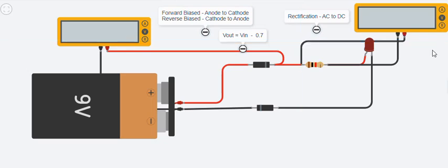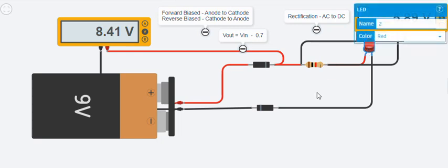It's usually called a current limiting resistor. Now 5.89, right? Yes. So 5.89 is what this is responsible for. The leftover is being shared by the LED and this diode. And what did you get there the other time? 2.5 something. 2.54, or 2.56.